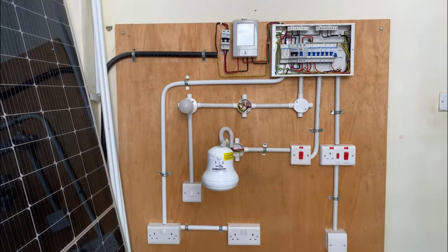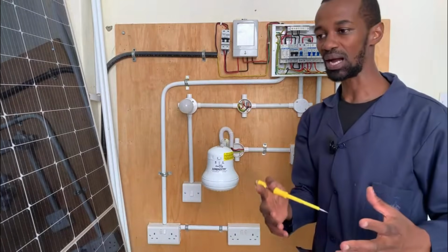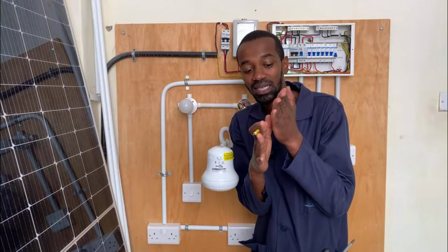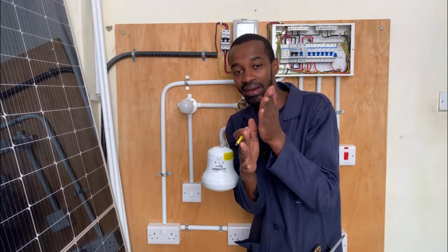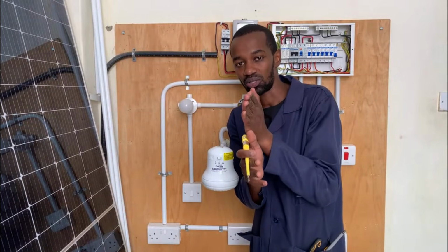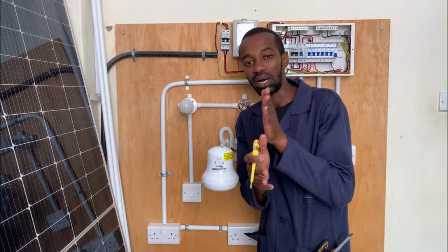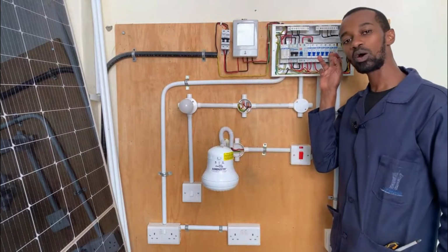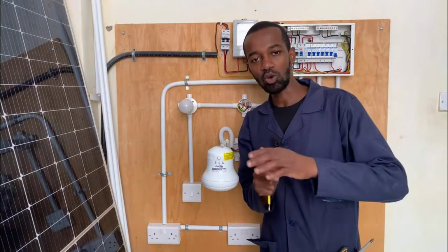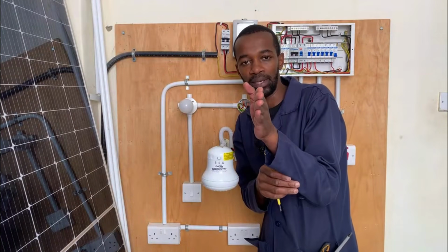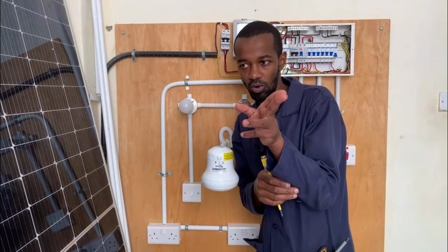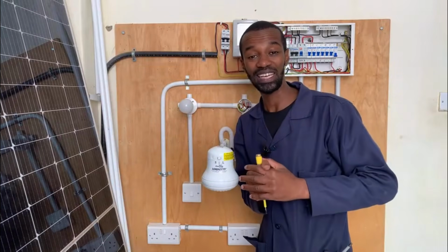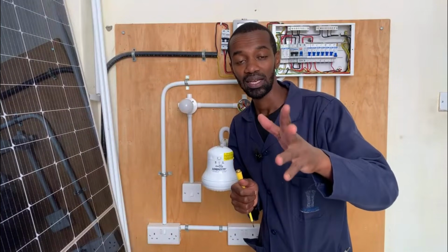Again, remember, in a house, especially these big houses, you'll find that there are several circuits. There is a circuit that is supplying the security lights and the common area sections. A smart electrician will ensure that that one is a single circuit served with one MCB. And then you have the sitting room and probably two of the many bedrooms, and then the corridor and the dining.